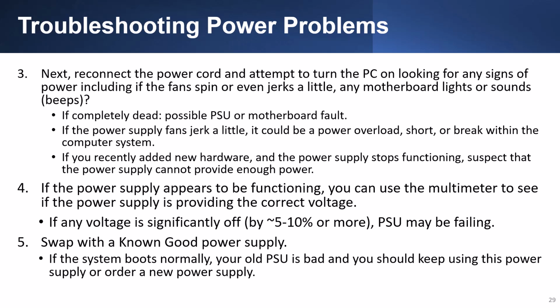If the power supply fan jerks a little, it could be a power overload, short, or break within the computer system. If you recently added new hardware and the power supply stops functioning, suspect that the power supply cannot provide enough power.